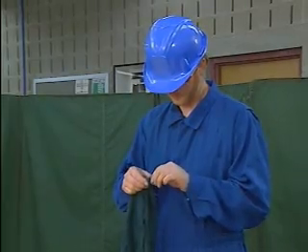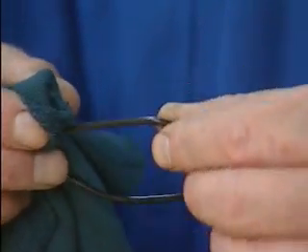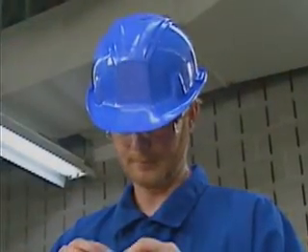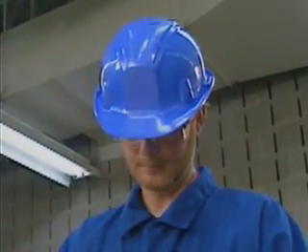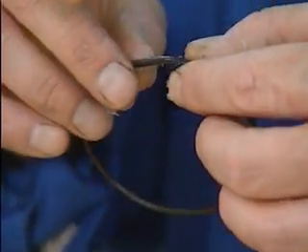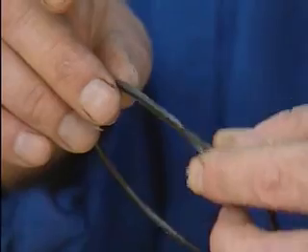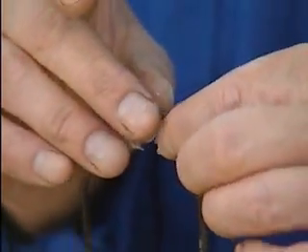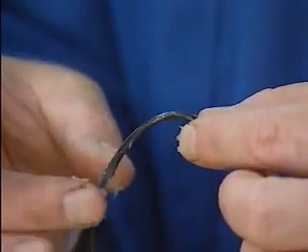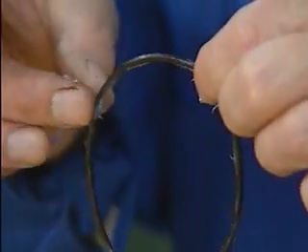Many O-rings, due to their rubber composition, have a tendency to stick or bind to metal sealing surfaces. Lubricant is often used to allow the O-ring to seat more easily during installation. The lubricant that's used must be compatible with the fluid in the system and with the material that the O-ring is made of. If the wrong lubricant is used, the O-ring could react with the lubricant and the O-ring could be damaged.